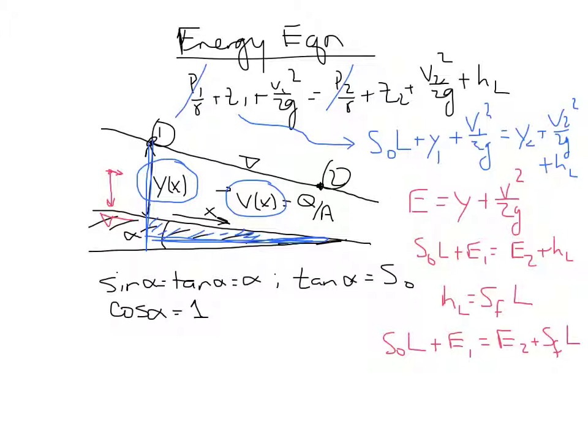And I'm going to leave it there in this review for today. What we're going to focus on in our next lecture is what happens if E1 and E2 are equal, so the depth is uniform. That means that we equate these two slope terms, and that leads us to a particular relationship. Later, we look at other perturbations to the flow that cause the depth to adjust. But for now, we'll just leave it with this energy balance.